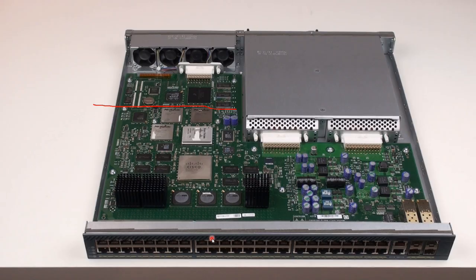To provide the copper ports, we need something called a PHY chipset. Here in this switch, it has 1, 2, 3, 4, 5, 6 PHY chipsets, which provide connectivity to these copper interfaces. The fiber interfaces, let's say the SFP interfaces, can be different types of SFPs. They don't need to go through the PHY ICs, because when you plug in an SFP, it also includes the PHY electronics. So the SFPs just go directly, probably over an RGMII interface, to the switching chipset.